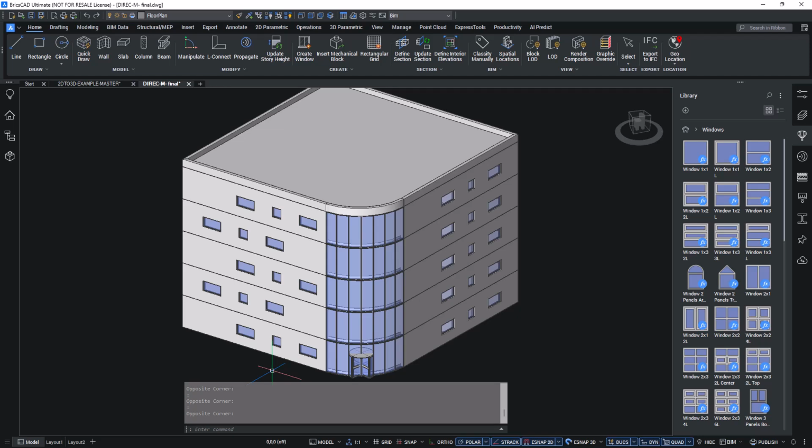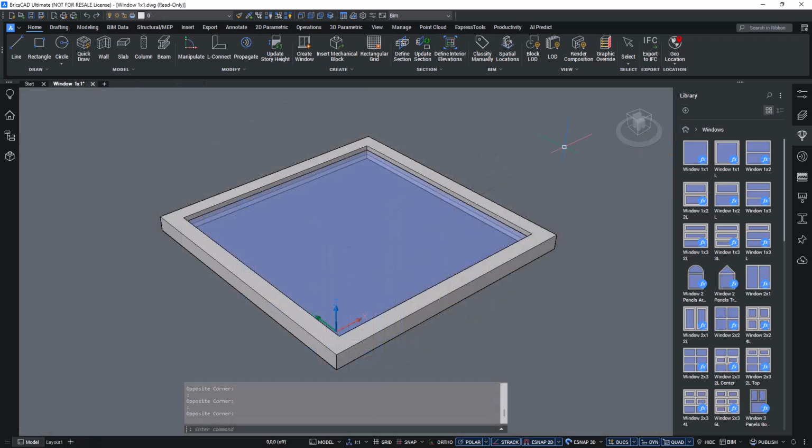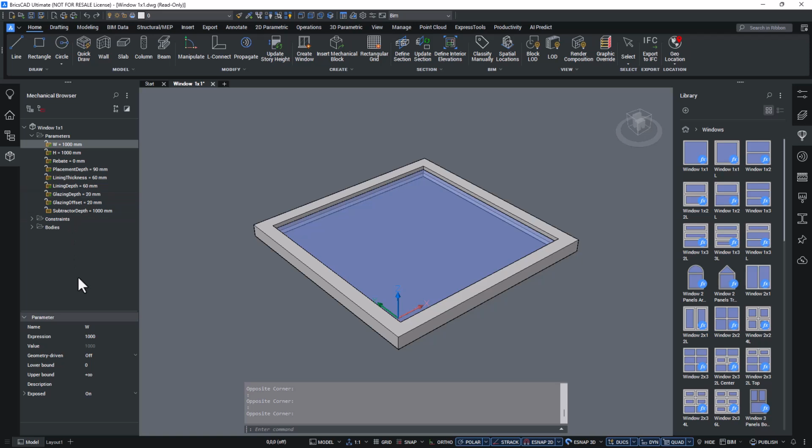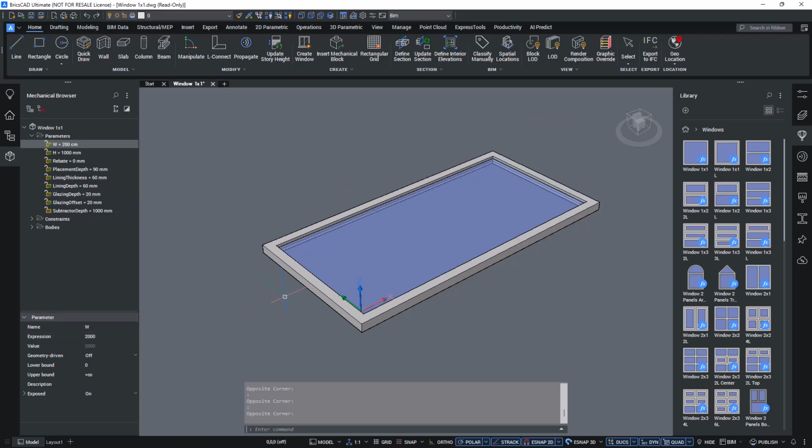To customize a beam block beyond its geometric parameters, go to the three dots next to it in the Library panel and click the Folder button. This button opens a copy of the beam block insert as a new drawing. After making the desired changes, open the Library panel and browse to the category where you want to save the beam block.